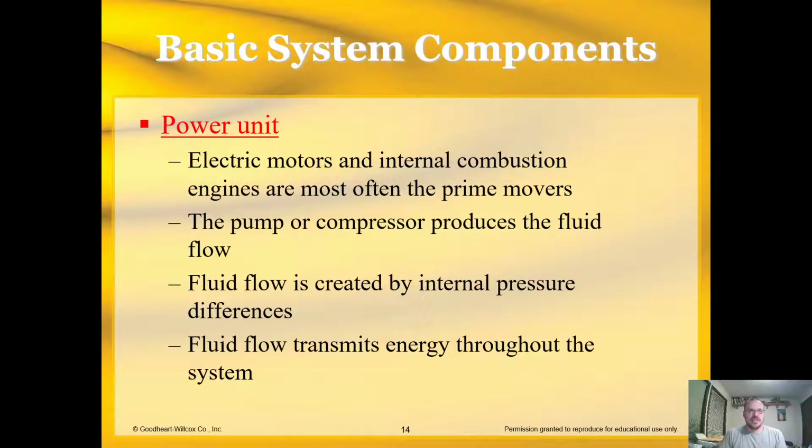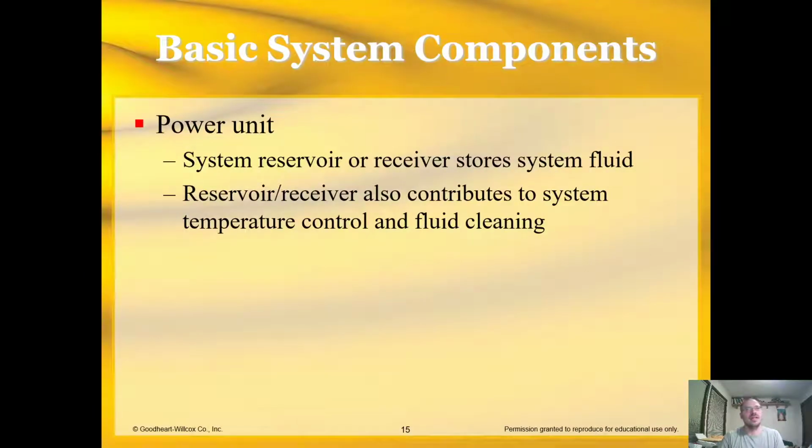Fluid flow transmits energy through the system. So your power unit essentially takes that energy, electrical energy or gas-powered energy, turns that into hydraulic energy, and then that gets transmitted to your actuators, which then do the work. Your power unit system reservoir receiver stores system fluid.